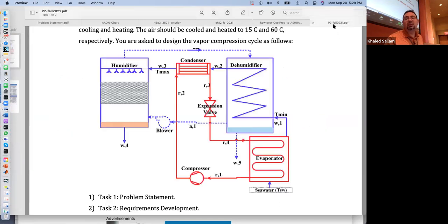So note that in this project, he's trying his best to use really hot water, but also the spraying part. When you spray the flow into a mist, into really tiny droplets, the evaporation happens so quickly. You still need to pay the hfg, but the rate is quick, right? But just atomizing doesn't mean that you are vapor, just that you have very tiny liquid droplets that still need their latent heat.